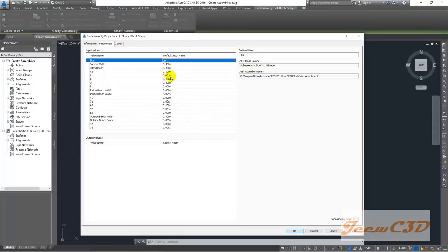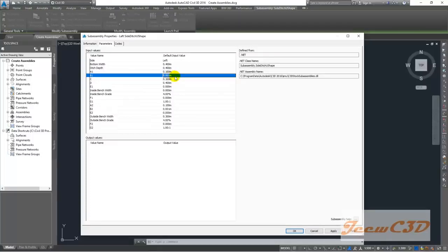I have used this 1 millimeter values because I can't use 0, it will get you an error. Instead you have to have very small value. I have put 1 millimeter to show you the value. So you can even put a value such as 0.00001 to get something close to 0, but you can't type exact 0 because it will give you an error.